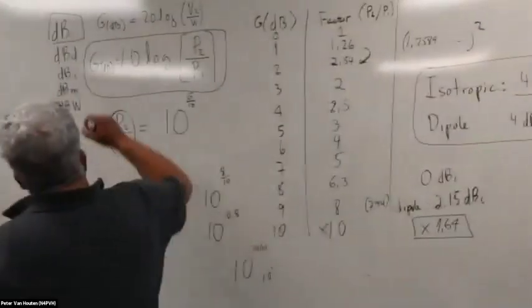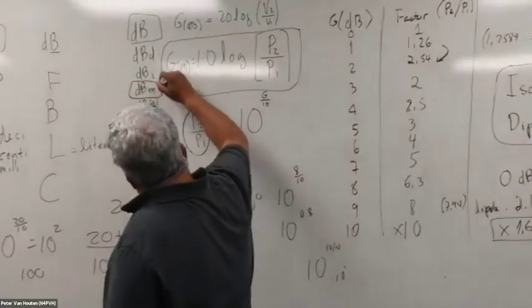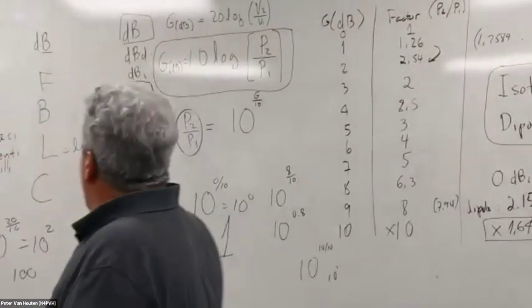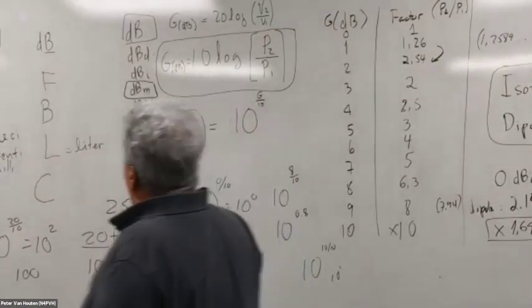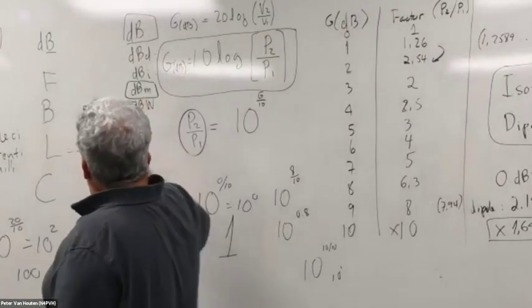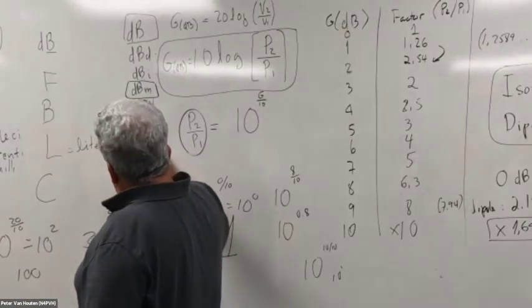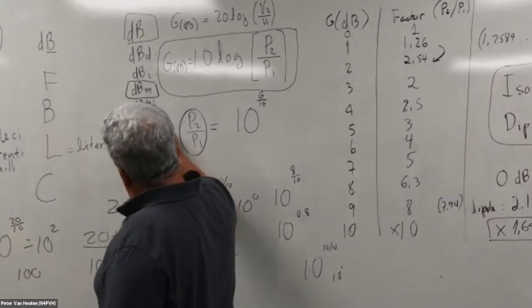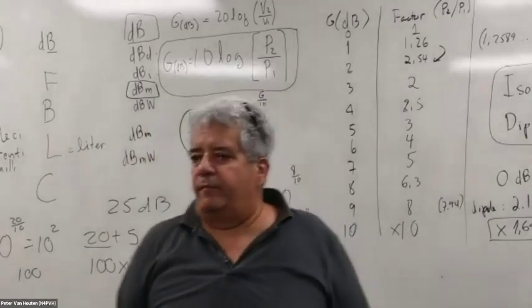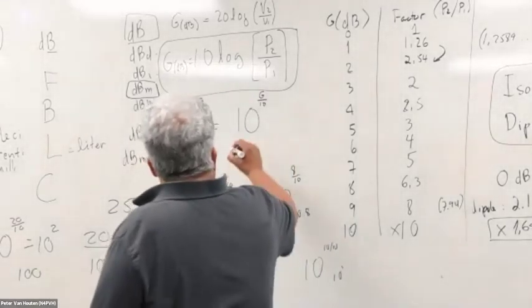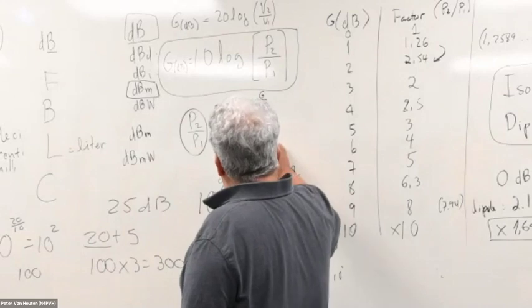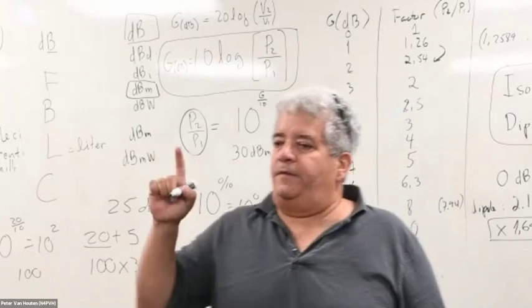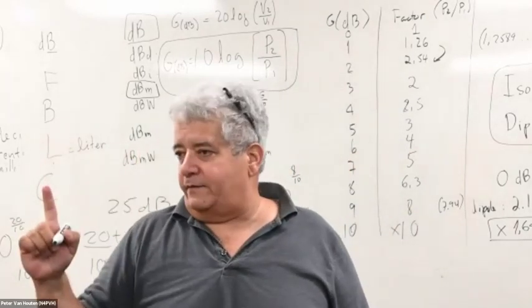And the other one, you don't see much, but dBm is used a lot in microwave and in general in radio frequency engineering. dBm means decibels over a milliwatt. It's expressed like dB and lowercase m, dBm. So if my microwave radio is transmitting with 30 dBm, that means the radio has a power of 30 dBs over 1 milliwatt.